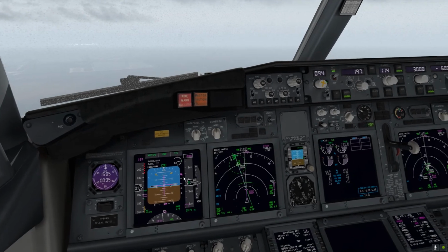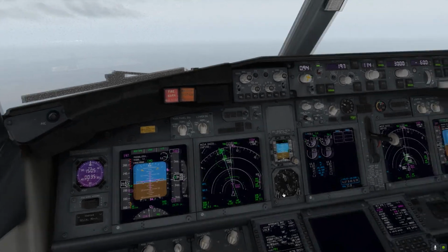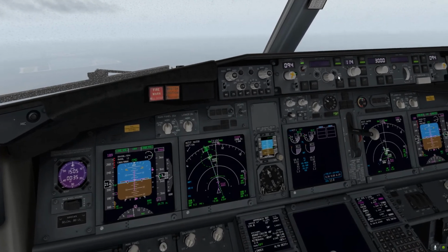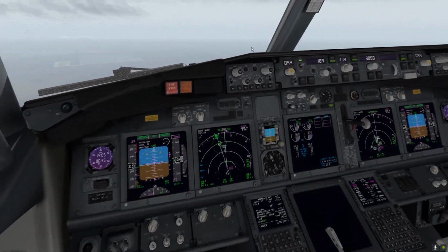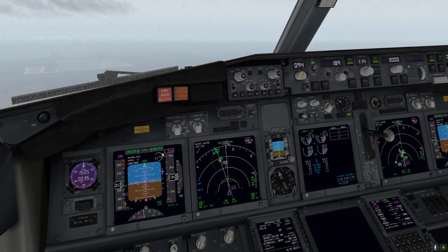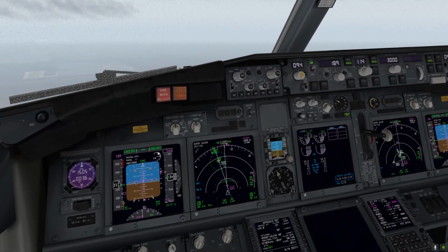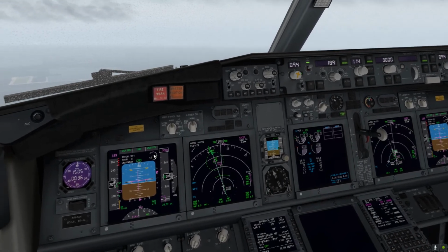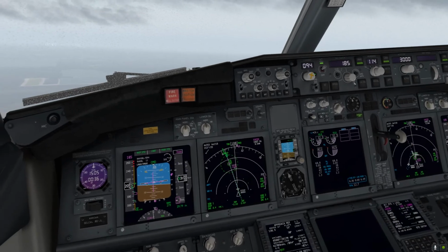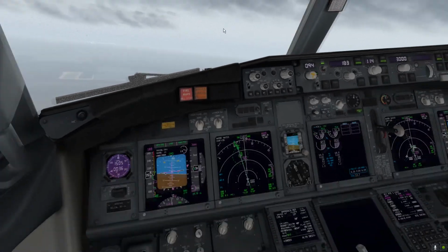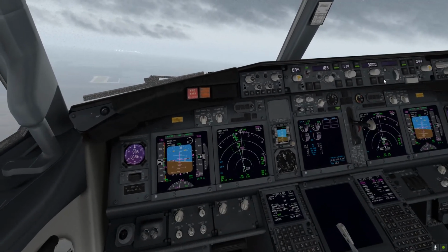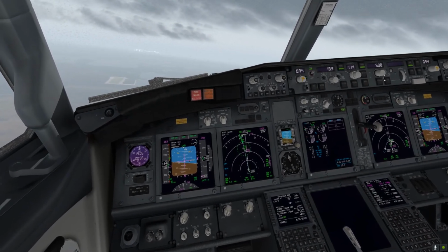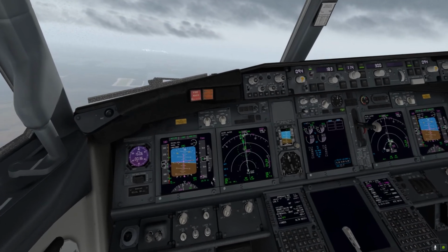Okay, the glide path is coming, as you can see also here. So we go like that. VNAV, speed intervention, VNAV path. Very important to monitor this VNAV path and not VNAV alt. Flaps 5. Yeah, about 185 knots will do. Unwinding speed, altitude to 300.